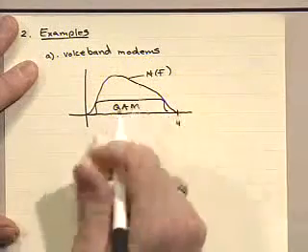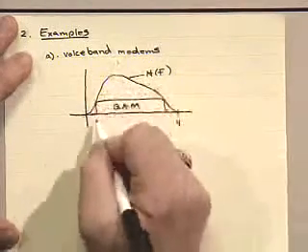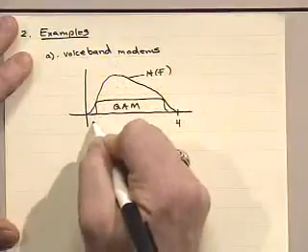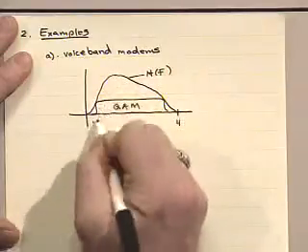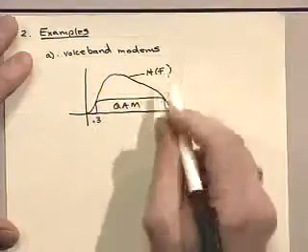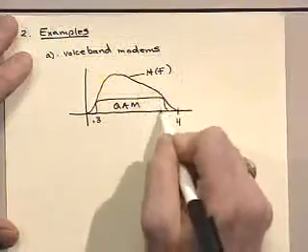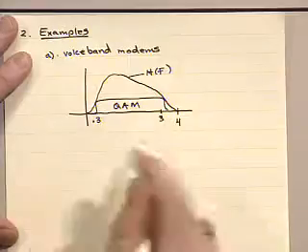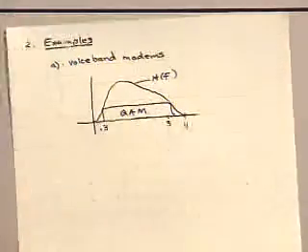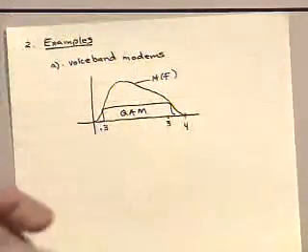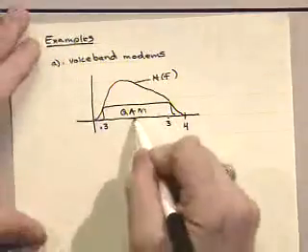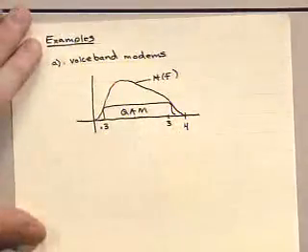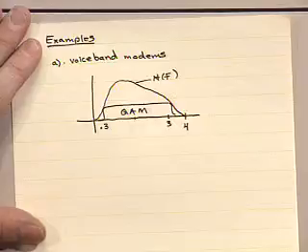It may go from frequencies as low as a few hundred hertz, so let's say 0.3 kilohertz, up to maybe a little bit above 3 kilohertz. So most of these modems will actually adapt the symbol rate and carrier frequency so they can try to fit the QAM signal into the channel like that.